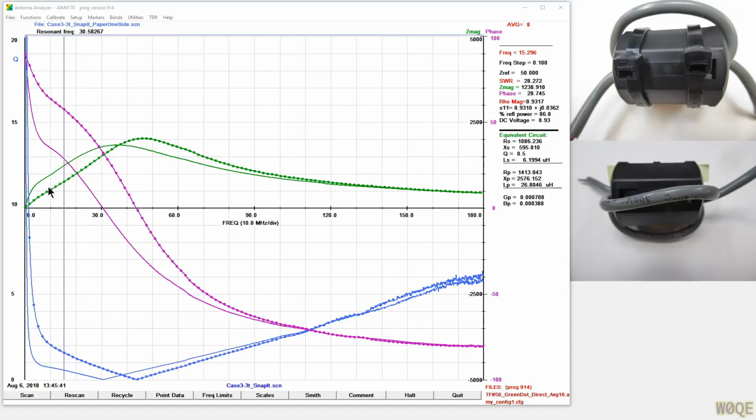We see a reduction in impedance of about 50% down at the low frequencies. So here's, say, 10 megahertz. It's just about half the value. Now at high frequencies, it's actually higher impedance than if the core was in contact with itself. But at lower frequencies, we lose a huge amount by having this open. And I also plotted one more. And that curve is the one with the cable ties around it.